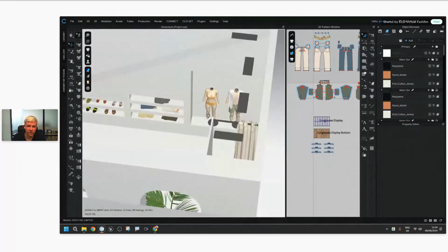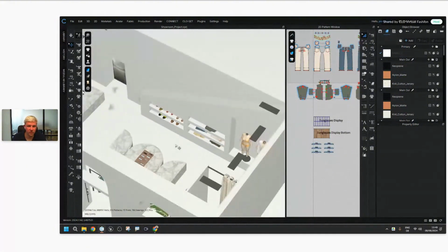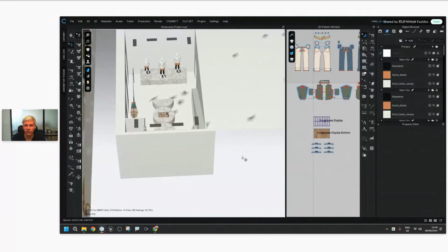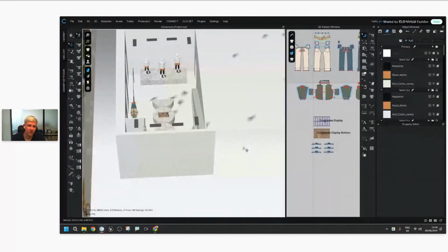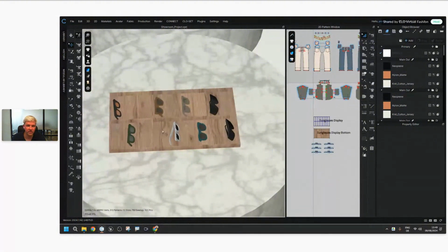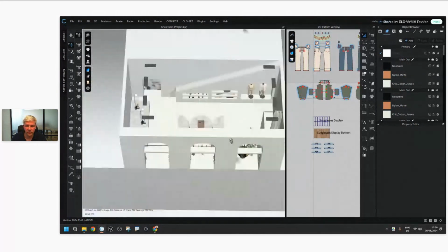And by the way, if you see something like strengthened or frozen, you've seen like it becomes orange or light blue. If you didn't know this, you can turn this off without unfreezing or unstrengthening. You can just, in an empty space in your workroom, right click, go to show hide color, and then you can hide specific things, but I want to say hide all. And then if I go back to my sunglasses, you can see that it is frozen, but it's not visible. So it is the original color. Okay, so far so good.